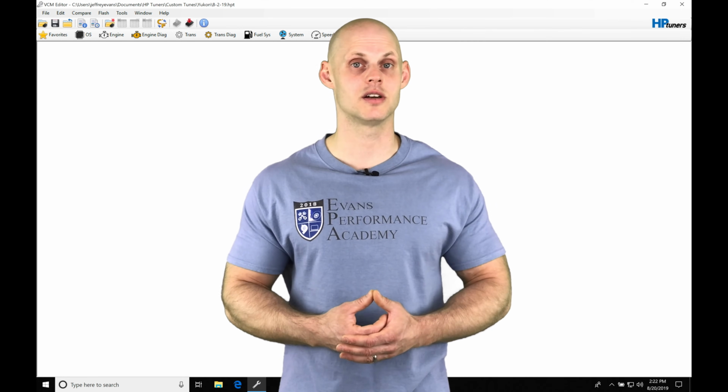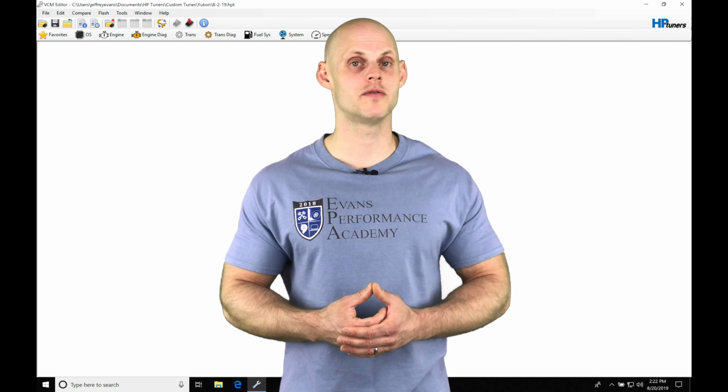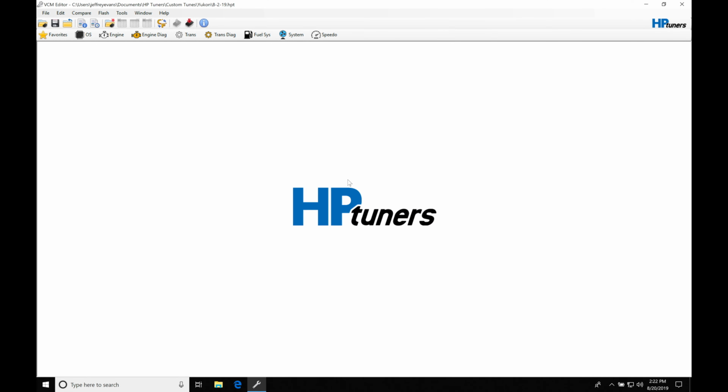There's going to be a lot of things to cover here with the knock control. So let's jump into our video so we can check everything out. Okay, so let's get started. We're going to be taking a look at our knock control in our GM Gen 4 ECMs. We're going to find that we have a whole bunch of tables to look at. We have to understand on a fundamental level how the knock control is going to work and what the tables are going to represent. So if we're going to be making any changes or updates during our tuning process, we need to know what tables to touch and what tables we need to leave alone.